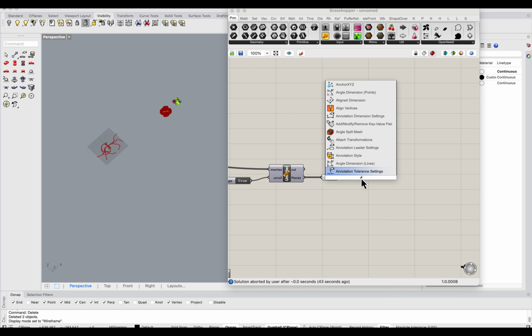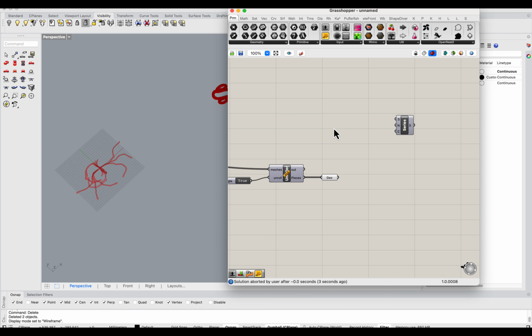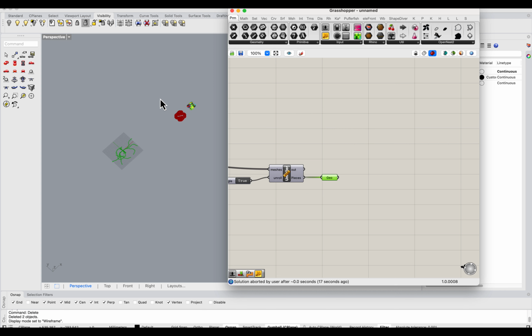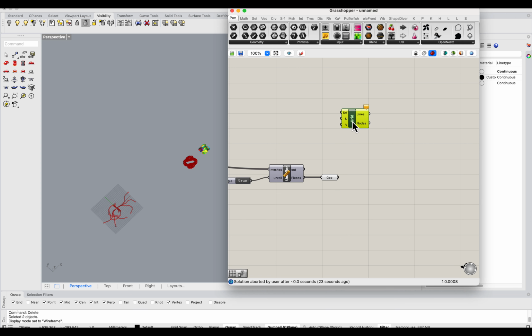For instance, I can take these and create like a series, and we can basically space them out in X or Y. Or if you know how many pieces you have, let's say I have 24 pieces here, I can create a grid of 4 by 6. So first, initially, we will be basically spreading these elements.